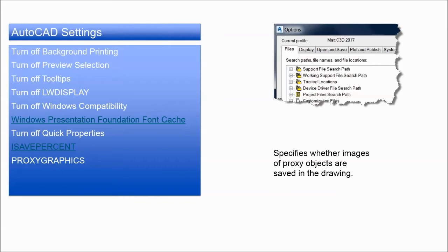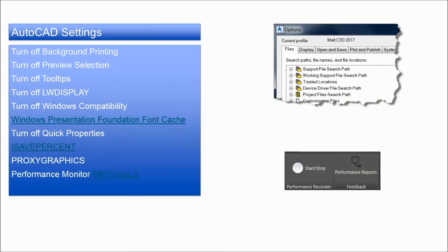If you have AutoCAD users in your office, you can install the freely distributable Civil Object Enabler that will enable the Civil 3D objects. So vanilla AutoCAD people will actually be able to see your objects.